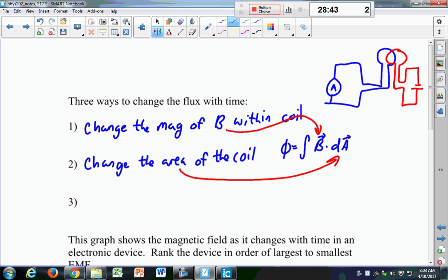How can you change the time? I don't know. That's interesting, right? I like that. But if you change the angle theta, then that will change the magnetic flux. So, right, that's what we do. In generators and the like, you crank it up, you get that gas-fed motor that turns the coil. That changes the angle theta of this coil with respect to this coil. So you can also change the angle.